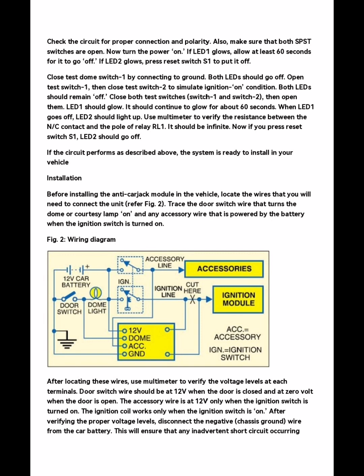Check the circuit for proper connection and polarity. Also, make sure that both SPST switches are open. Now turn the power on. If LED 1 glows, allow at least 60 seconds for it to go off. If LED 2 glows, press reset switch S1 to put it off.